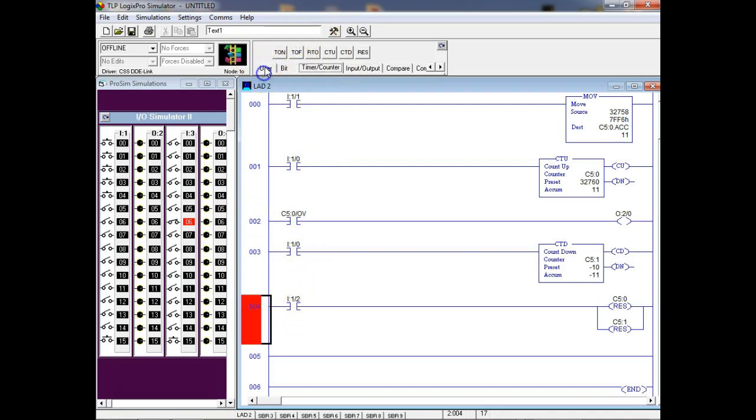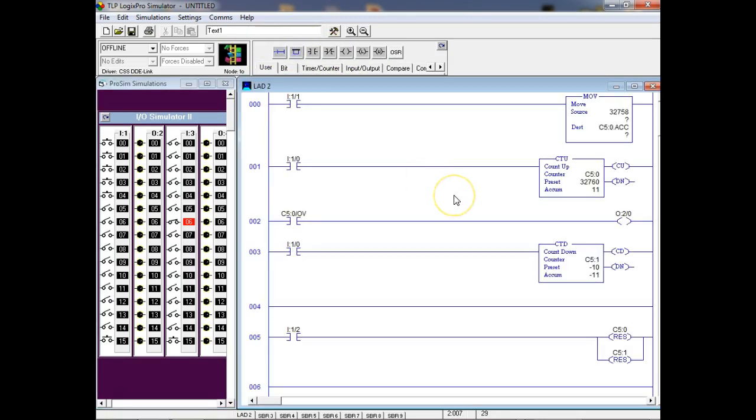So if we wanted to look like what we envision a down counter to be, so what am I going to do, Rich? I'm going to come up. Well, that's the same thing, true. That's like saying it's how many up counters you need, right? Yeah. Understand? I'm just showing you how you can make it more logical. So we'll just put another button in here. Which one? I'm going to use 15 down here just for the heck of it. So I'm going to put input colon 15 slash, I'm sorry, not 15, 1 slash 15.